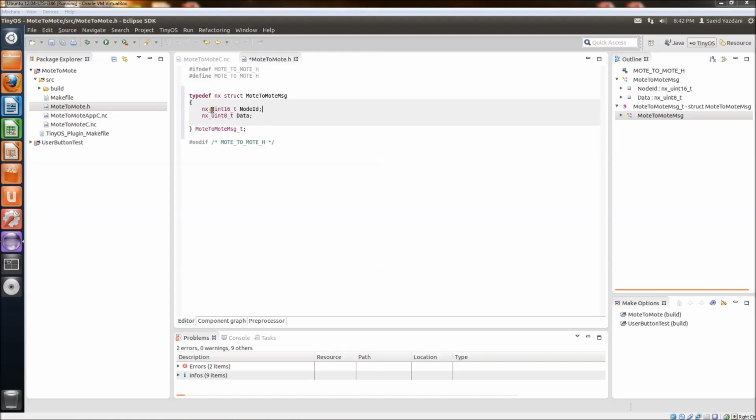But just for now, think of a radio packet that contains the ID or number of the transferring sensor board, and it also carries data, so we can store in this part of the packet a number, because it is unsigned int of 8, and it's 8 bits, so we can transfer something like between 0 to 255. You will see later how it works.